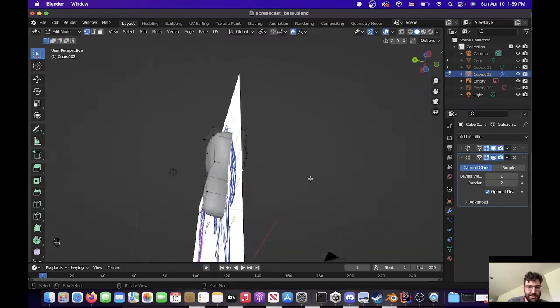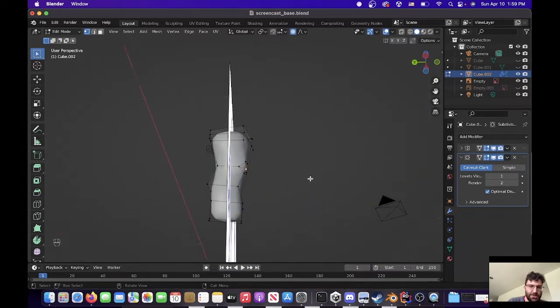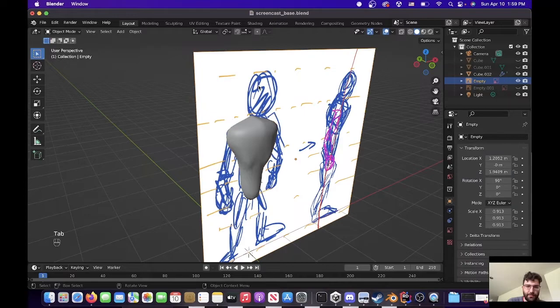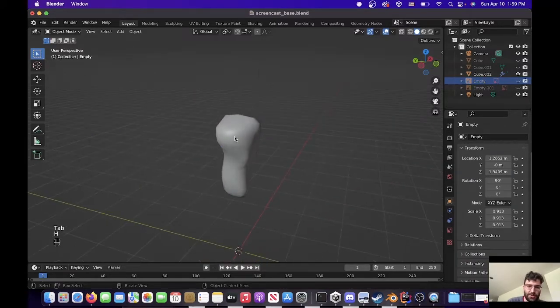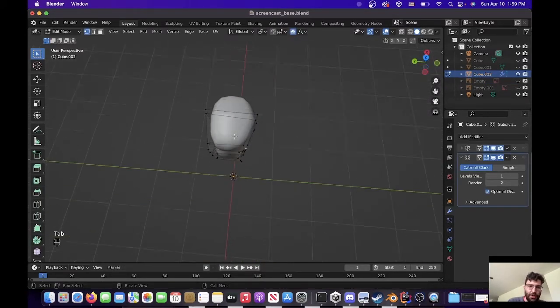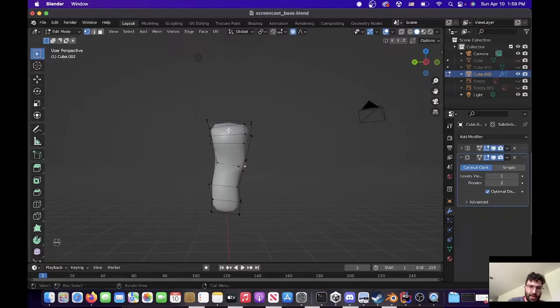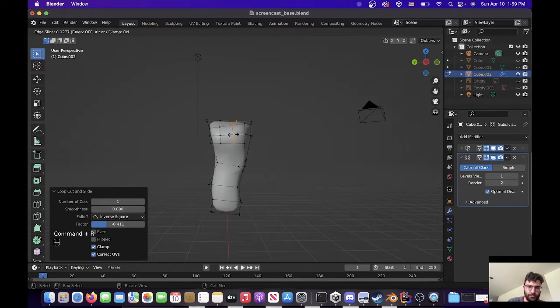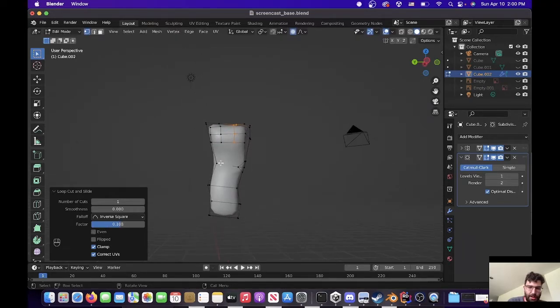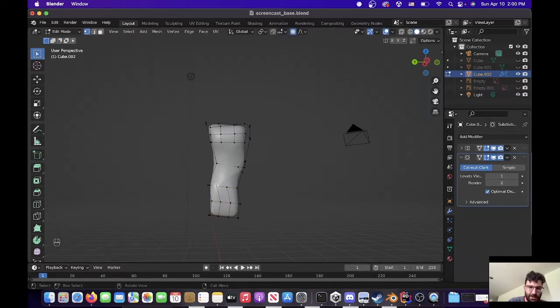What's also missing is legs. So we can literally just repeat that process we made for extruding the torso with extruding legs. What we want though is geometry for, we want 2 loop cuts sort of going like that. And because the geometry of our mesh isn't ideal, Blender couldn't auto-identify all of this stuff, but that's okay.